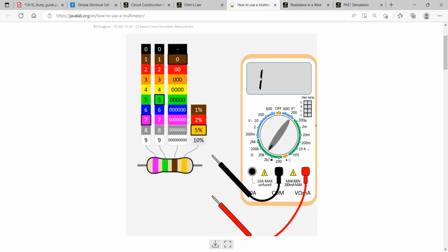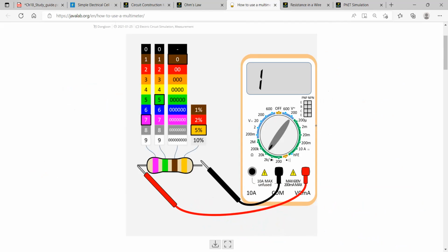So if I use the probe, you see that it is 0.7, and here because it is in kilo. Okay, so it shows that the resistance of this sample is 0.75 kilo, and 0.75 kilo ohm means 750 ohm. Okay, so it matches. And because it is simulation, there is no tolerance. Although we use tolerance here, there is no tolerance here.